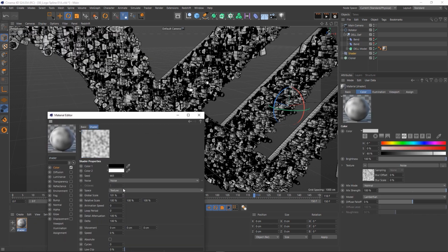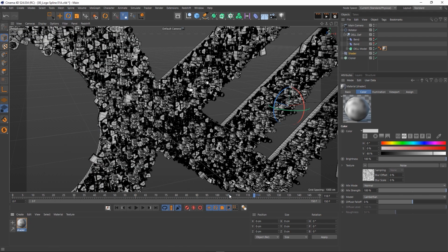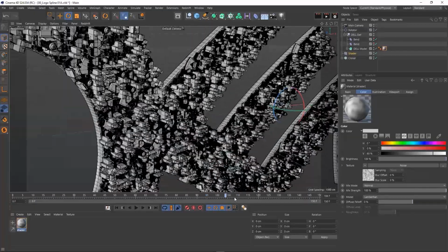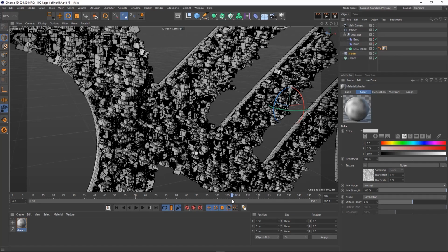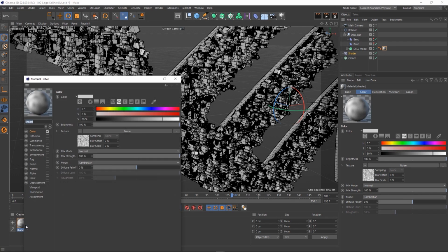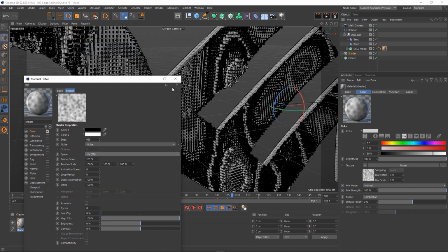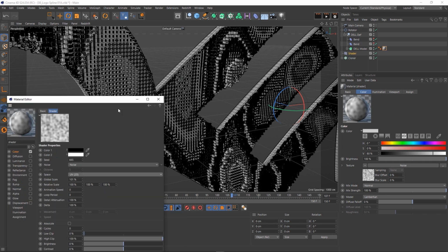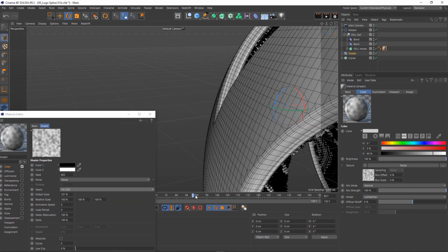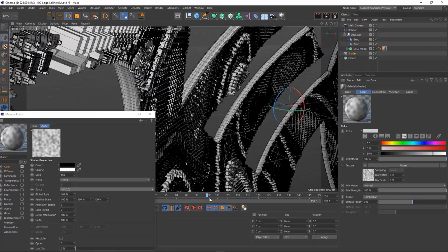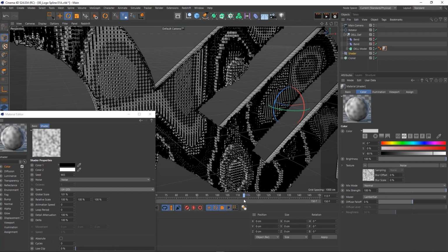So if I go here and I change the scaling and stuff like that. Now there's one little detail you need to be very, very careful with, because watch this. When I start deforming this, these buildings are creating chaos. They're changing. And that's because the noise currently is sampling the world. Anyway, that's a detail. Just go to the noise itself and change the space to UV2D. And this will fix this noise on the surface it's getting the information from.